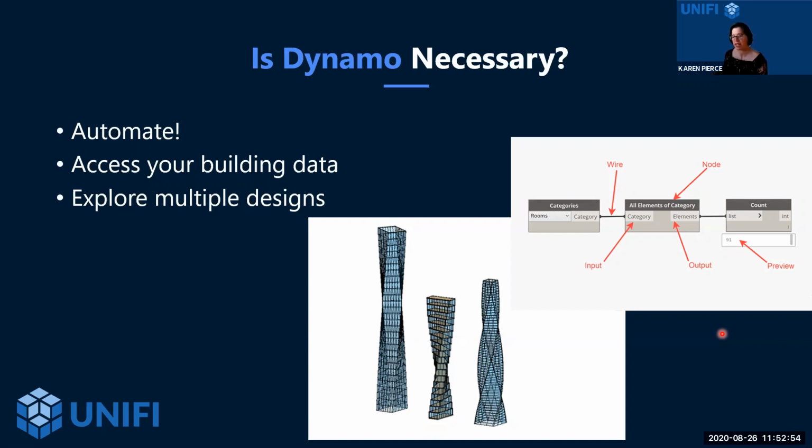The other one is to actually start from the end. So like you see here, let's say I wanted to push parameter data into my room schedule from my floors, something like that. While I would be tempted to say, I know I need rooms because that is what I have to ultimately push into, what I might actually want to do is ask, what is that final block that I might need? And actually work your way backwards.